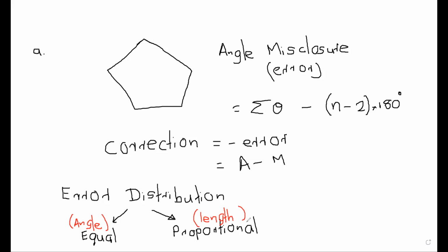Then you are reading 10 as 11, 5 as 5.5. All your readings would be the real one multiplied by 1.1. When you measure 1 meter on the tape, it would be 1.1 meter, if you extend the same tape.